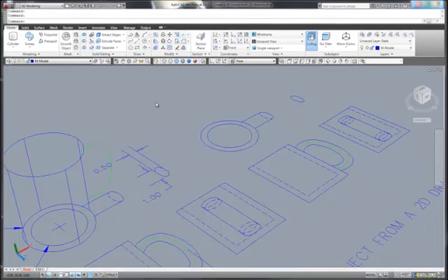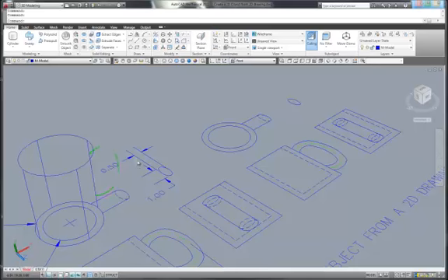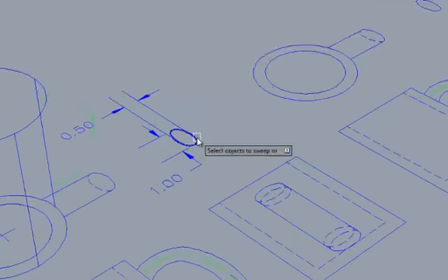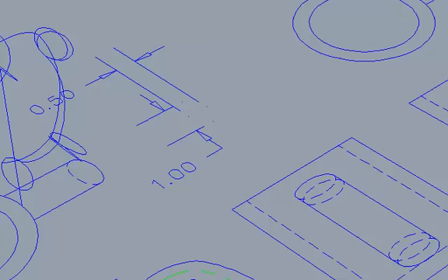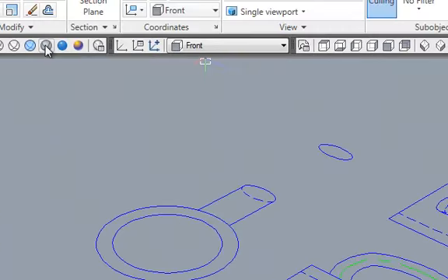So here we are again, and we're trying to attempt how to sweep this here, and we're going to find out why it is or isn't sweeping. So we're going to select our object to sweep, and then hit enter, and then we're going to select our path, and there it did. Okay. Let's take a look at that in grayscale, and that's looking pretty darn good.